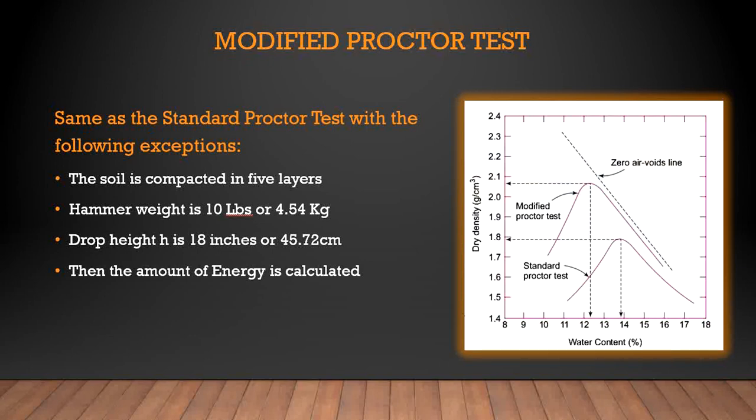And the moisture content dry density relationship, that is nothing but the compaction curve, may be obtained by adopting a similar procedure as in the previous case. Since the compactive effort is more for this test than for the standard Proctor test, the compaction curve in this case may be expected to lie higher when superimposed over the curve for the latter, with the peak placed to the left.